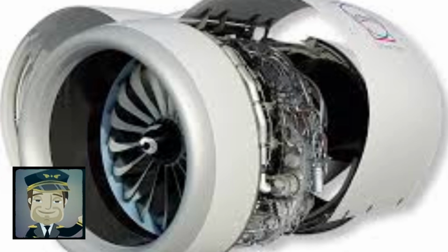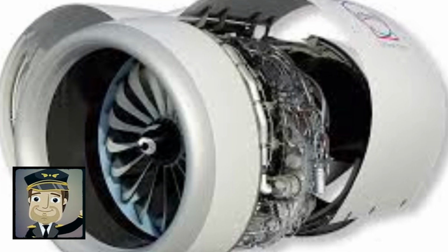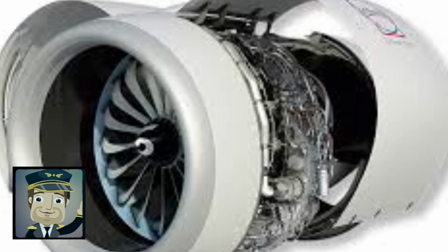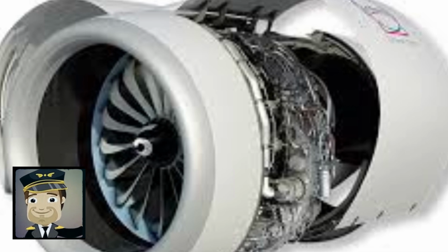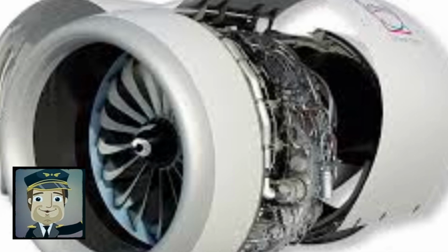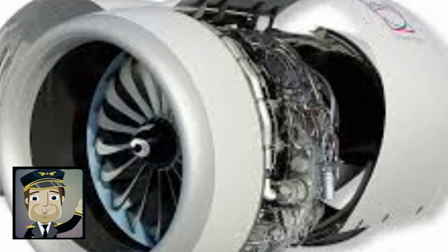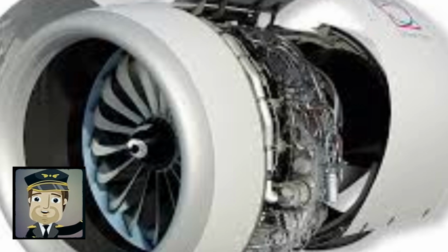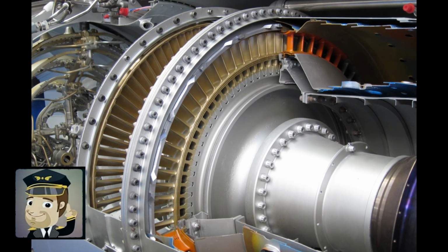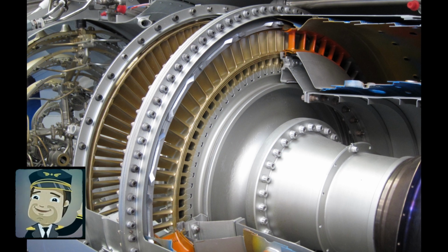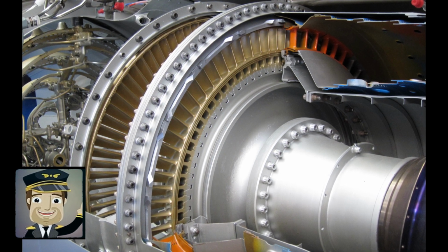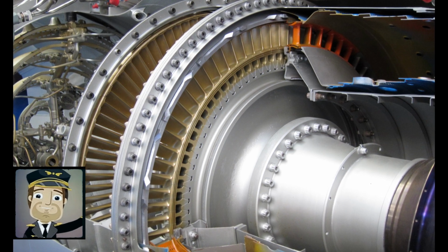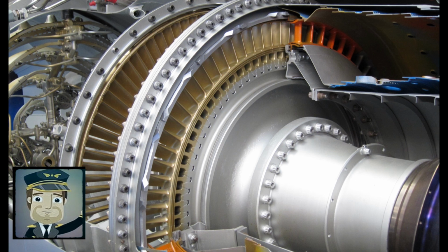Nearly stoichiometric turbine entry temperature approaches the theoretical limit, and its impact on emissions has to be balanced with environmental performance goals. Open rotors, lower pressure ratio fans, and potentially distributed propulsion offer more room for better propulsive efficiency. Exotic cycles, heat exchangers, and pressure gain/constant volume combustion may improve thermodynamic efficiency. Additive manufacturing could be an enabler for intercoolers and recuperators. Closer airframe integration in hybrid or electric aircraft can be combined with gas turbines.